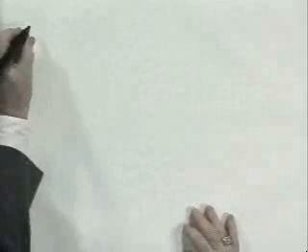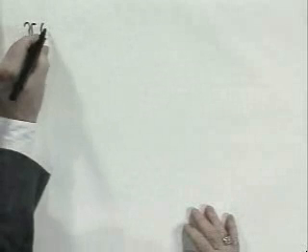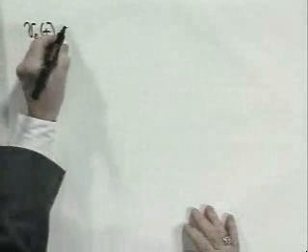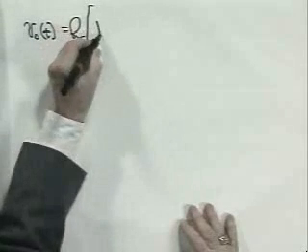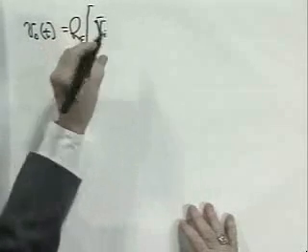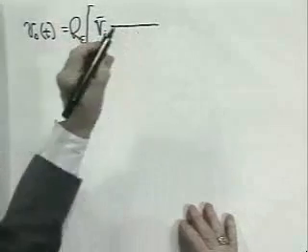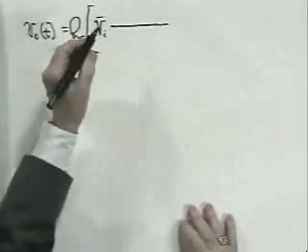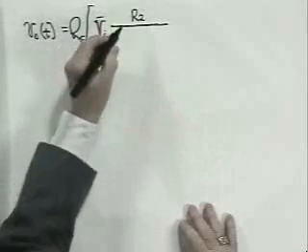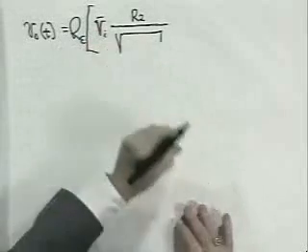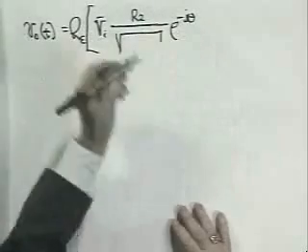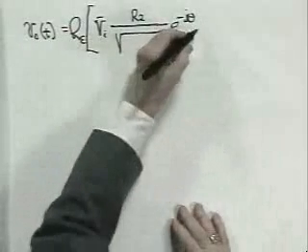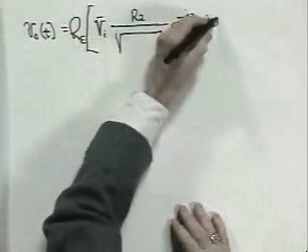So as the last step in this process, we can write the time function v sub o of t as the real part of the magnitude of the input, v sub I, times the magnitude of the voltage division ratio, R2 over the radical, times e to the minus j theta, where I defined theta on the previous page, times e to the j omega t.